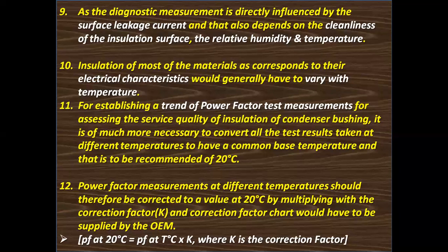So, for establishing a trend of power factor test measurements for assessing the service quality of insulation of condenser bushing, it is much more necessary to convert the test results taken at different temperatures to a common base temperature, and that is recommended as 20 degrees centigrade.